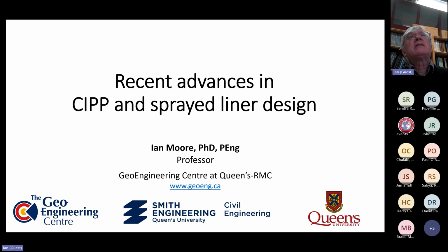But if we're tunneling so that we're excavating the whole of that section and then we're slowly going down it with depth, we'll tend to produce a much longer wavelength behavior and significantly less demand at the joints. So I'm trying to describe it with words. Of course, I don't have a picture to show you, but hopefully I'm making sense.